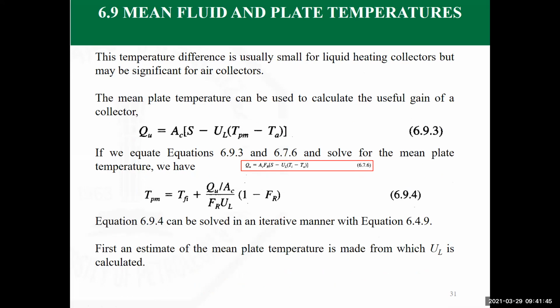I would probably have mentioned that the efficiency of the collectors is given in figures by companies producing solar collectors for the American system based on the inlet temperature. In the European system, it is based on the mean temperature. So now companies, when they are producing their units, try to give the efficiency expression in both, so that their collectors can be sold in Europe, in the United States, and the rest of the world as well.